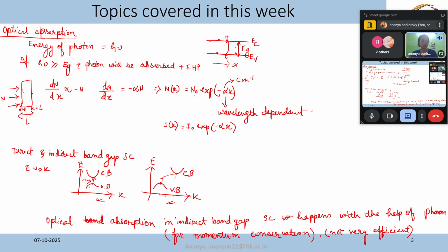So overall we get a higher recombination lifetime. That is useful because the electron and hole pairs will not recombine that easily, so we will have a large number of electron and hole pairs for a longer amount of time. So people try to use it, because even though silicon is an indirect bandgap semiconductor, people are using it for optical applications also, in solar cells.